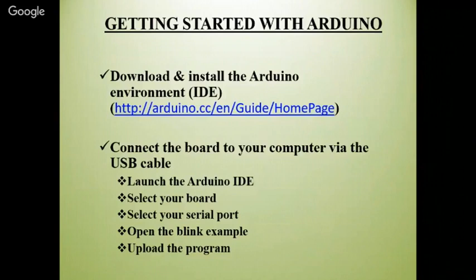You have to select whether you are choosing your Arduino Uno or Arduino Mega. If you have not selected the board, then there is an uploading error, because Arduino doesn't know which board you are using, as many other boards are there. Then select your serial port, the USB port on which your USB device is connected.